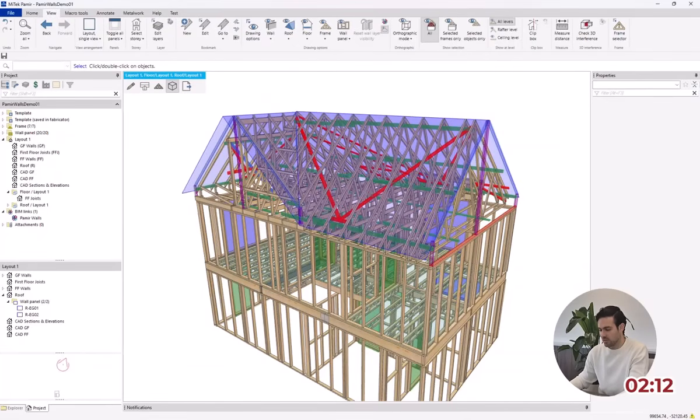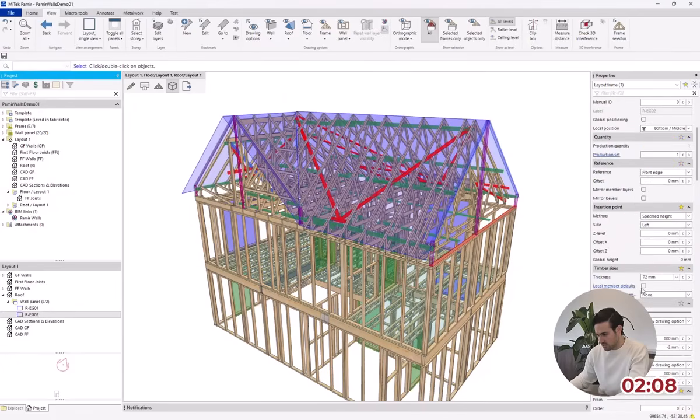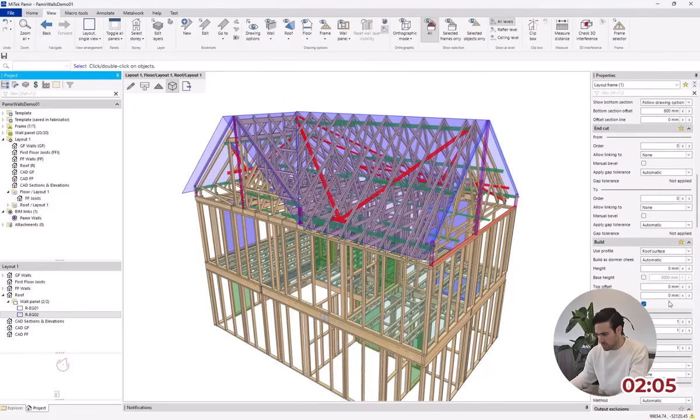The 3D has always been a great visual aid to make sure we have the correct heights in. From here I can actually see one of the spandrel needs an offset, so it sits on top of that supporting beam. So I'll just put that in, and now they are ready to build.